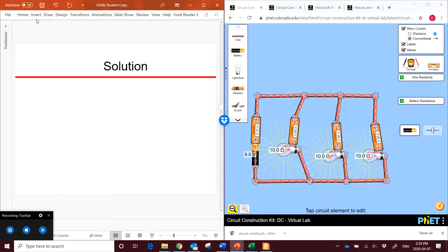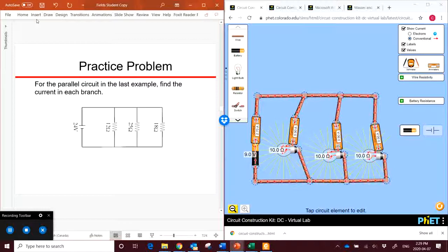And the last example here is to calculate the current in each branch. So we have our total current. Now what's the current along each branch in this system? If we want to know the current in branch 1, we have to use the voltage in branch 1 along with the resistance in branch 1. The voltage we know is the same everywhere, so 24 over our resistance of 12, and we get a current of 2.0 amps. Follow the same thing for the second two, so I2, and we end up with approximately 1 with some rounding, and I3 is 1.3.